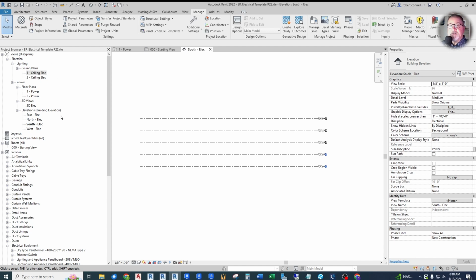There's a lot of options for naming views. The ones I've seen most typically used are names that help sort your views in an order. Some people will use a sheet naming convention. If your lighting plans are always the E2 or E200 series, you can put that here as well as in the sheets. And that way people know that these are E200 sheet views.